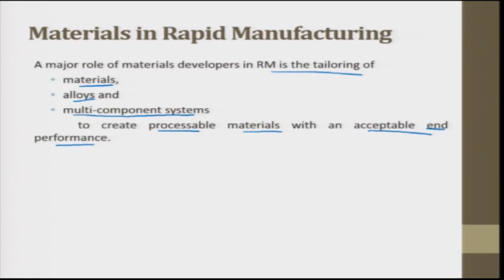As in the case of any manufacturing process, the choice of material is partly dependent on the specifics of the process. For instance, as fluidity is critical for casting, plasticity is a requisite for forging. Rapid manufacturing processes impose constraints on the range of available materials. So, the end use of the product is a critical factor in this.